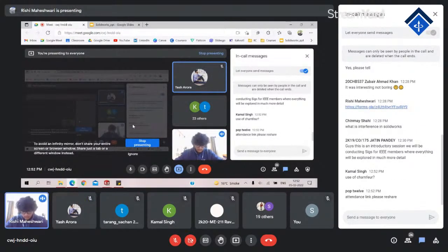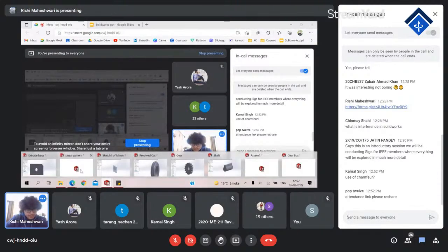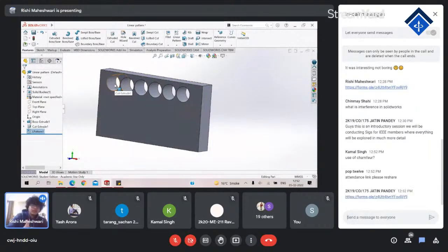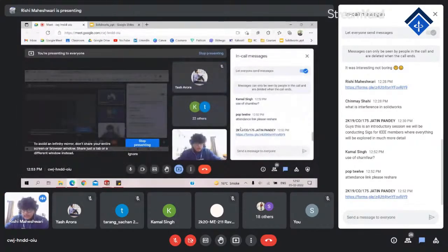Right. So in direction one, let me show it to you. Direction one, I selected this one, so the hole would move to the right, parallel to this particular edge. If in direction two I had selected this edge, then it would be replicated over here and here also. So you're just making another linear pattern. That's why there are two different directions provided to you. Okay, great. Thanks.